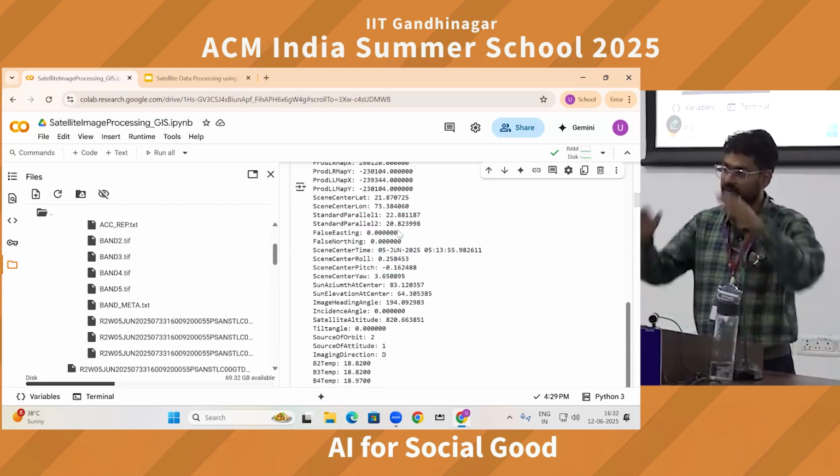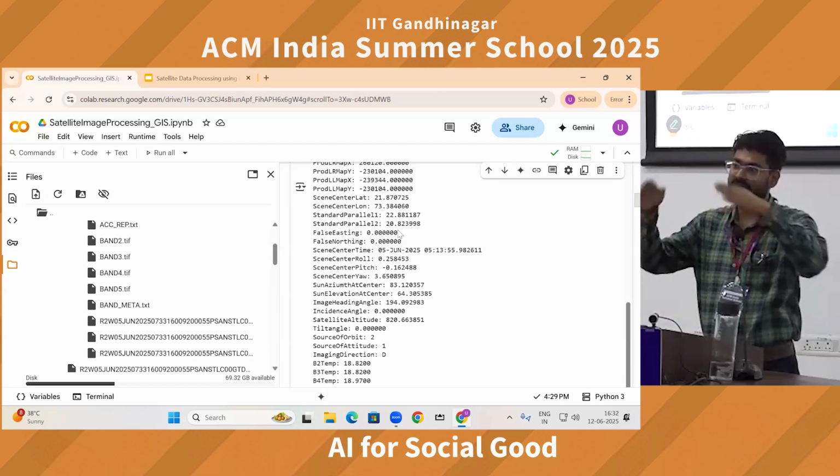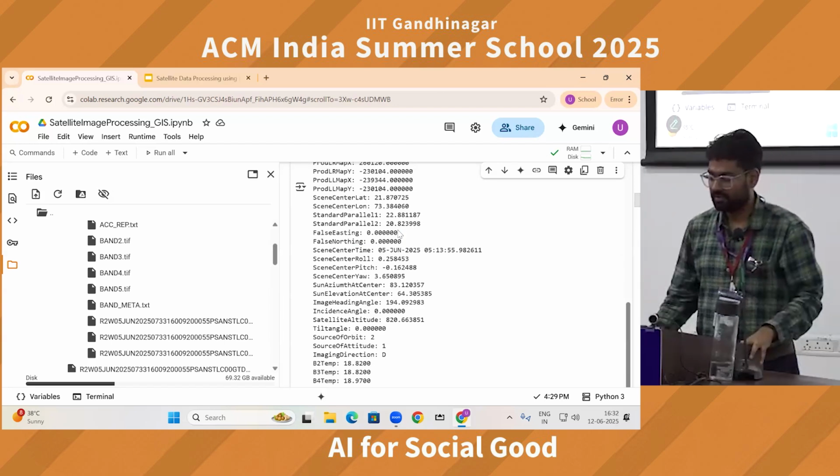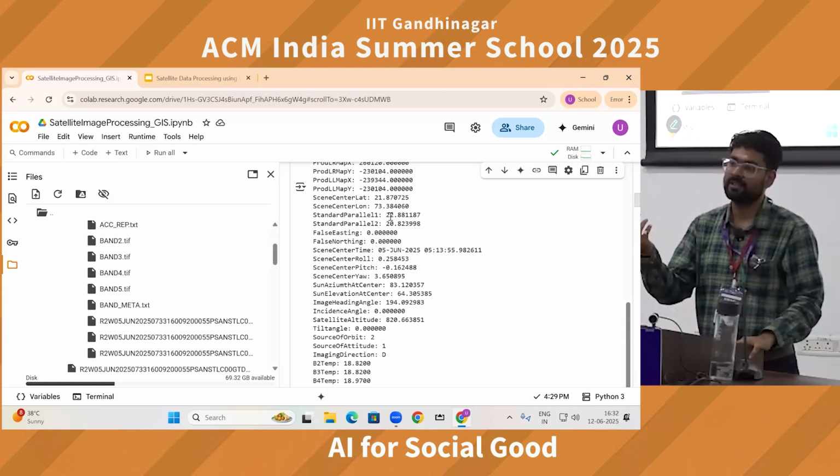Because it is a conical projection, you have to give standard parallel 1 and 2, because there are two directions in the cone which will be touching our surface. So that's why we have standard parallel 1 and standard parallel 2. These are the projection parameters. Some other projection you may not see it.